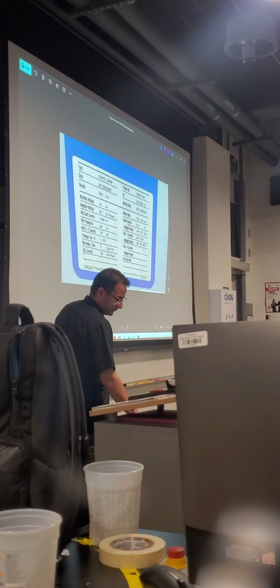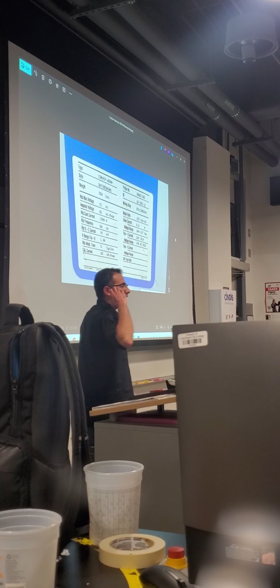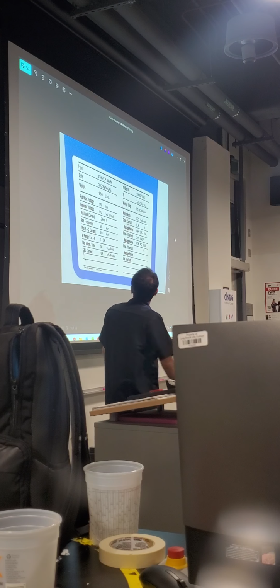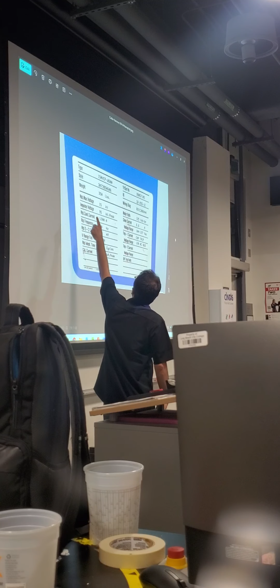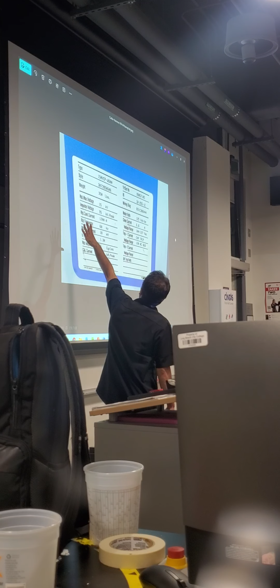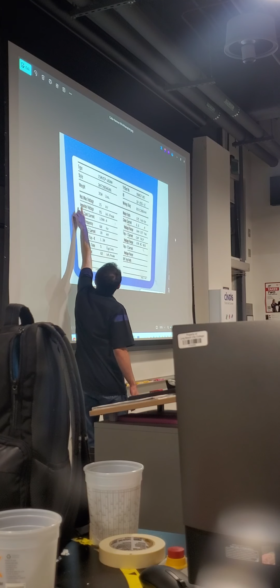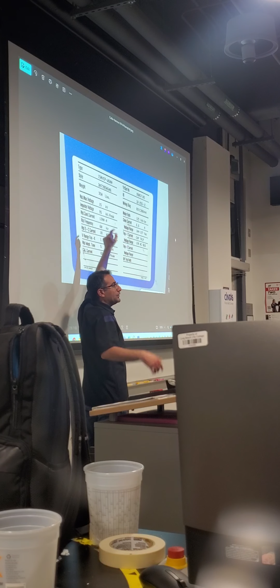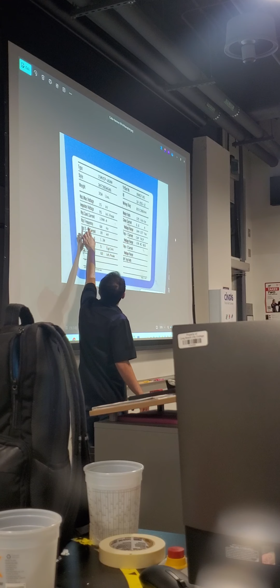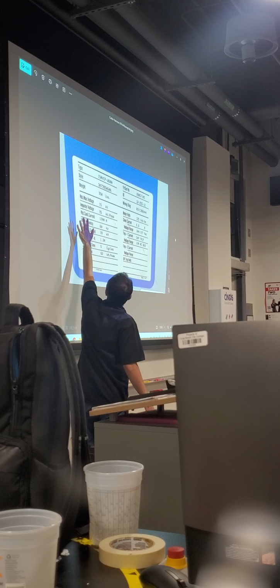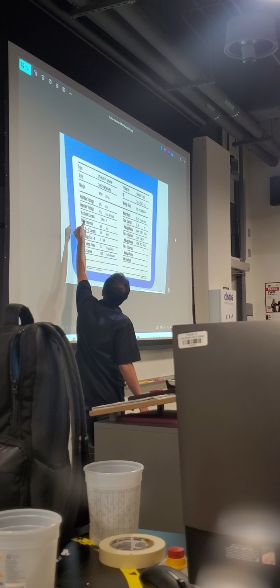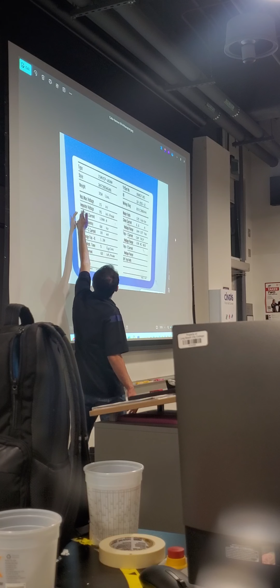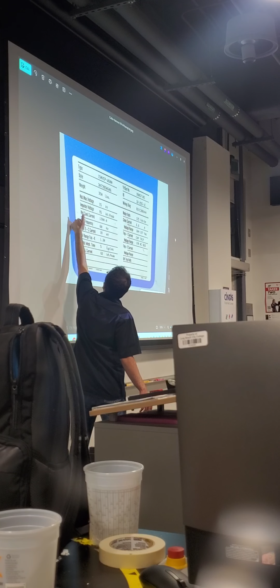Now, assuming this circuit breaker is AC, this is the nameplate of the breaker. It's already on Canvas, you can take a picture yourself. You have the type, and you have the rated maximum voltage. 15 kV is the maximum, but the operating voltage is 12 kV typically, 12.4, but 15 is the maximum rated voltage. The impulse voltage is momentarily for the lightning. It can tolerate up to 95 kV.